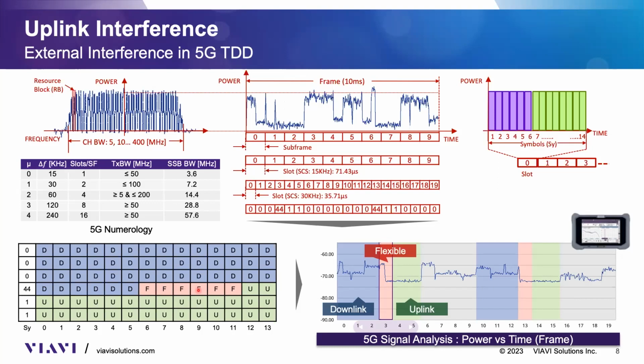So if we have an external interference transmitting, this is going to be my ideal time that I can assess for that external interference. Why? Because then I'm not going to have any signal from the radio as downlink, nor any signal from the UE as uplink. So everything should be clean during this period of time. And again, making the assumption that everything is properly synchronized.